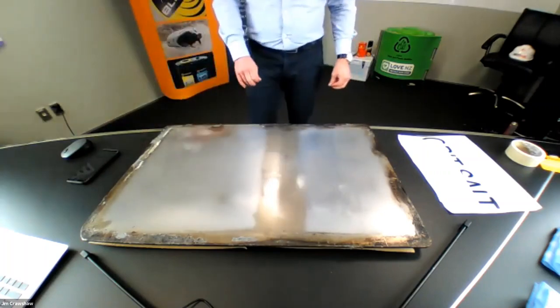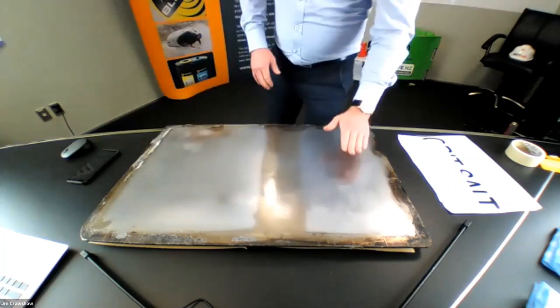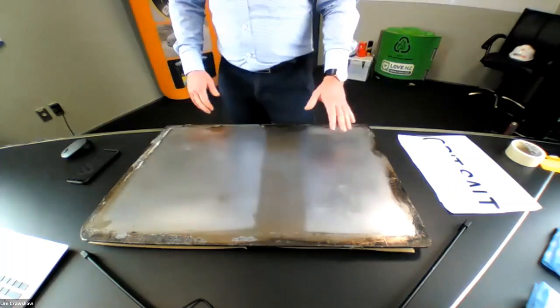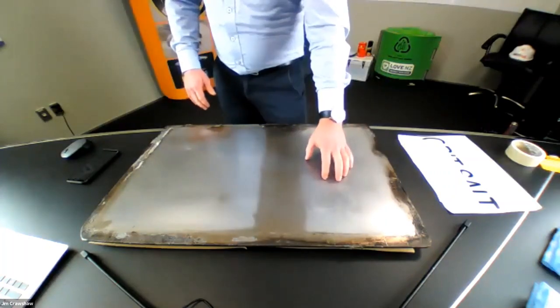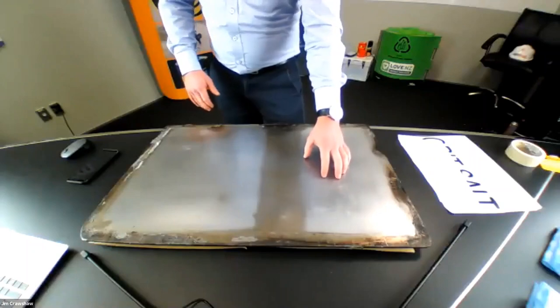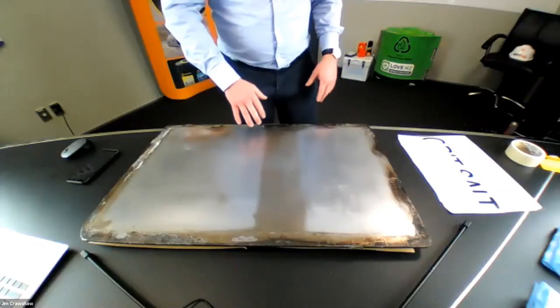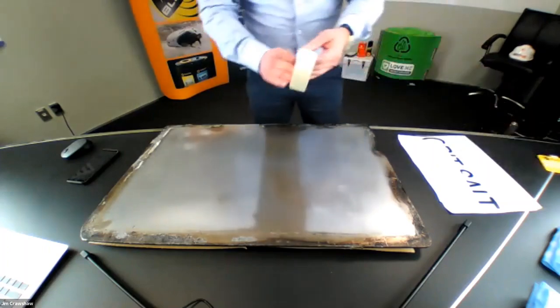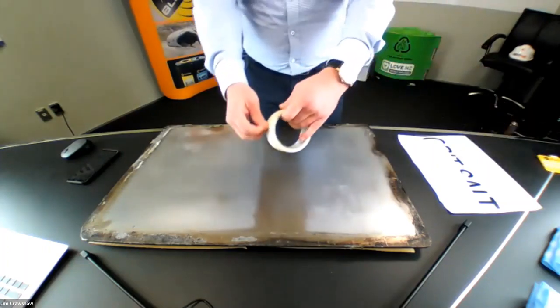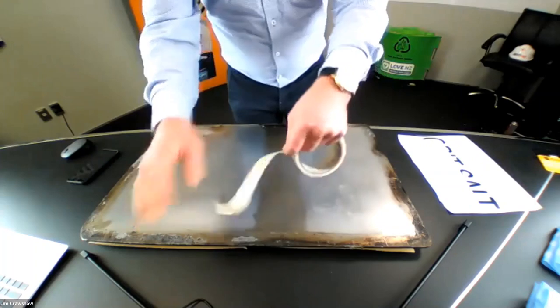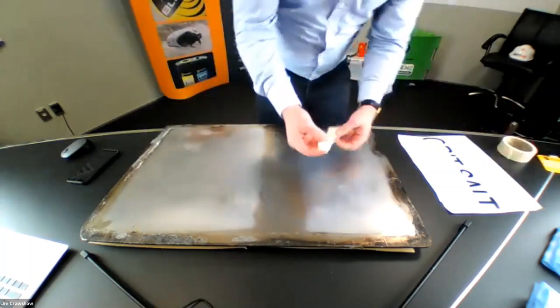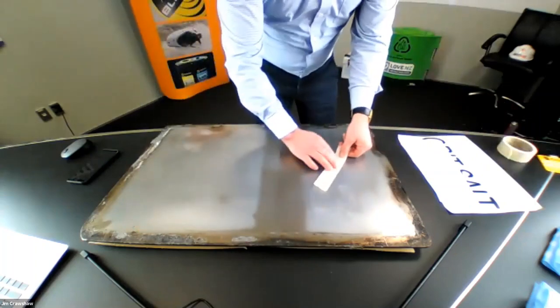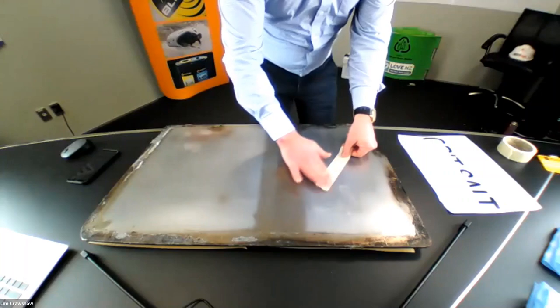So first up, we talked about preparing the mold. On this side here I've applied some release agent to it, and I'm going to show you exactly what happens when you do the tape test. Here I've got some paper masking tape, and I'm peeling a bit off and applying it onto the mold like this, and you can see it doesn't even want to stick there.